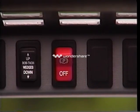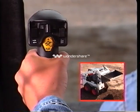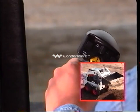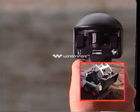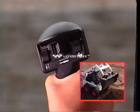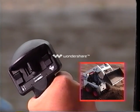Move the left hand control lever to the left to raise the lift arms and move it to the right to lower the lift arms. Move the right hand control lever to the right to tilt the bucket or attachment forward and move it to the left to tilt the bucket or attachment backward.